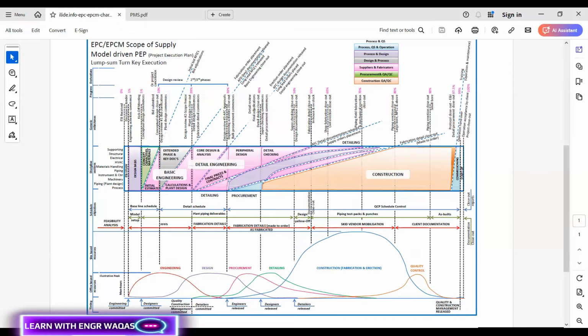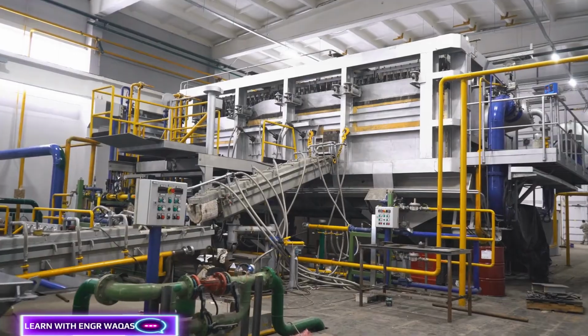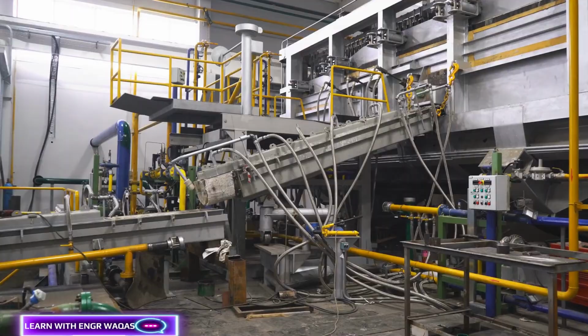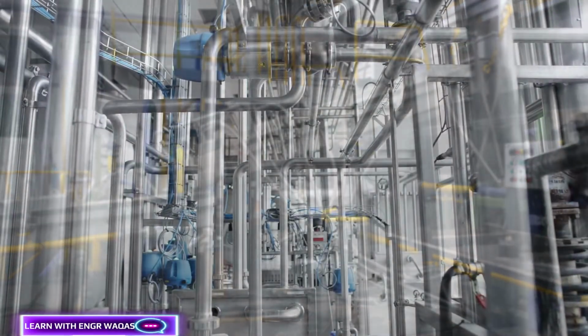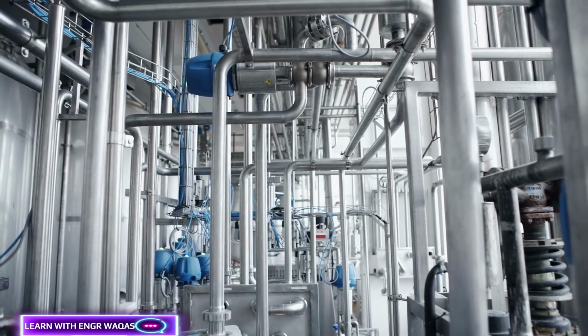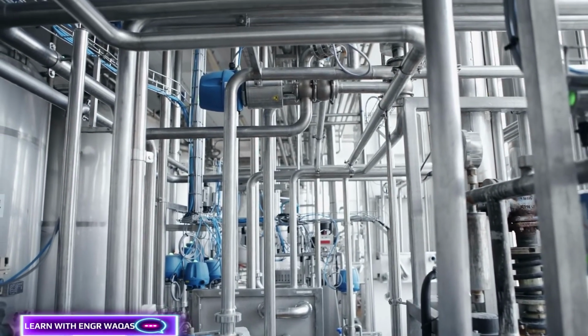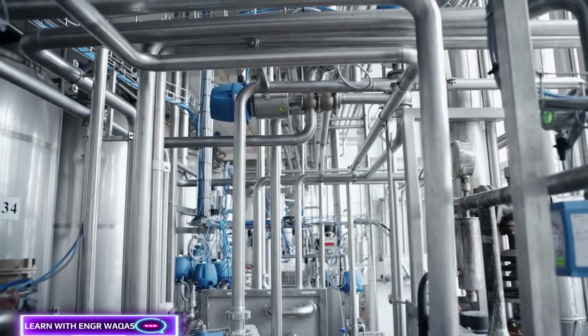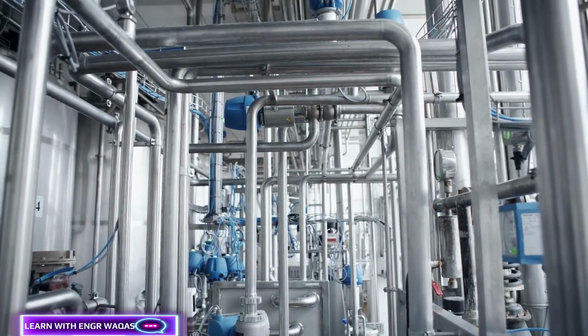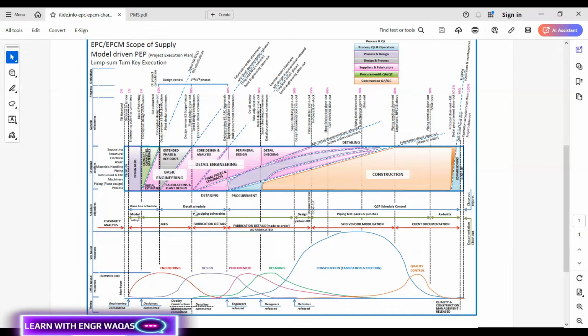So line list and valve schedules. You can see that the line list categorizes all pipelines in the plant by size, like 2-inch, 3-inch pipe, 5-inch, MR NACE, MR0175, H2S oriented, something like that. Okay, material, service and all that, right? Then flange and bolt schedule. Obviously, there are different kinds of pipe schedules, like 80, 120, XS, something. As-built drawings are also part of this deliverable. Quality control, quality assurance. So this one plant piping deliverable is carrying all this documentation.